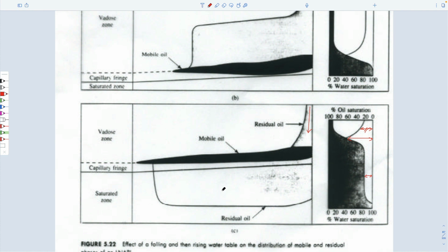And so now, I guess the ramifications for what we know with Darcy's law is if you have a gradient of flow here, and here you do have a gradient of head, right? dH dx. You can imagine from Darcy's law that you get minus K over rho G dH dx.